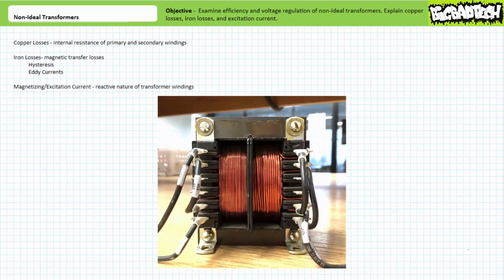While we're on the subject of wires, it should be noted that a transformer's primary and secondary windings are electrically insulated from one another. These windings are electrically insulated from the core, and the wires within the same winding are electrically insulated from other wires in that same winding. In order to keep cost and weight to a minimum, these wires are ordinarily not coated in plastic insulation, but rather a thin, electrically non-conductive varnish. This varnish, while cost-effective, can wear out over time, especially for a transformer that carries a large amount of current or is routinely overheated. A loss of this insulating varnish is often the principal reason for transformer failure.